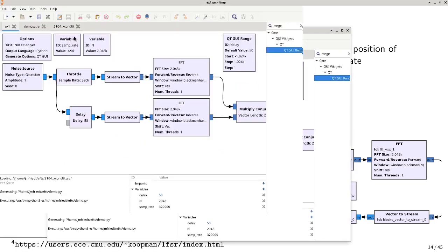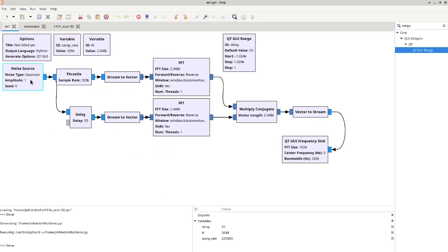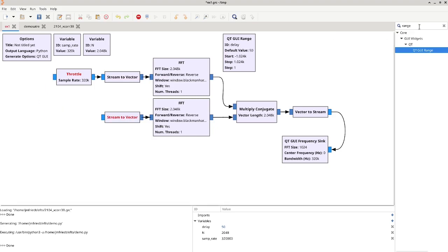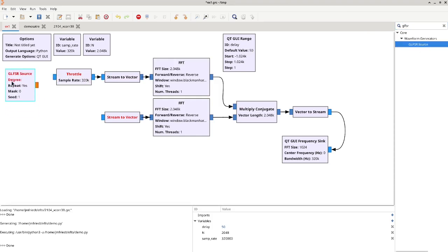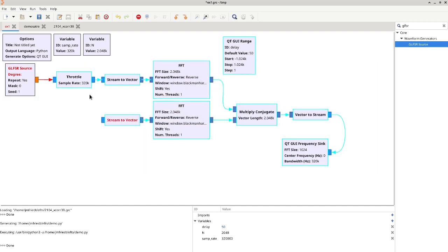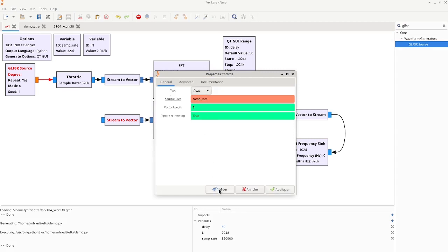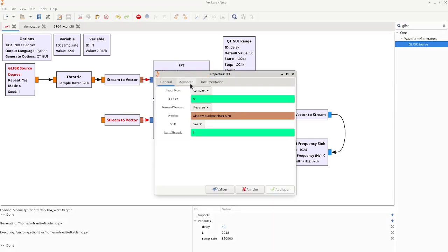So starting from our previous example, rather than using a noise source which is difficult to share with the users on the ground segment, we will have a reproducible way of generating random non-repeating sequences with an easy way of sharing with the ground segment the definition of these sequences. The Galois linear feedback shift register does provide such a capability in GNU Radio, with the output being a floating point number, which is not compatible with the complex quantity that has been involved earlier.